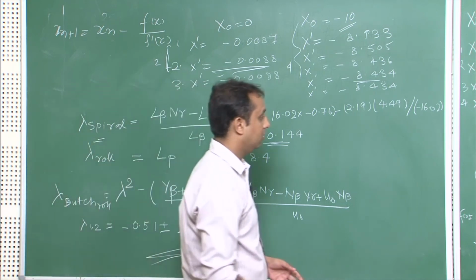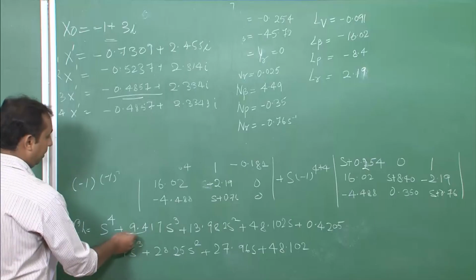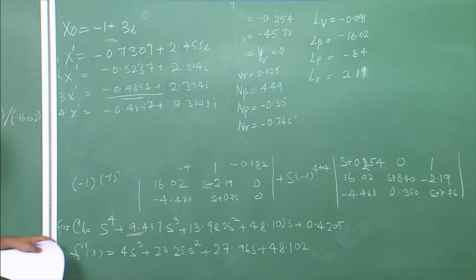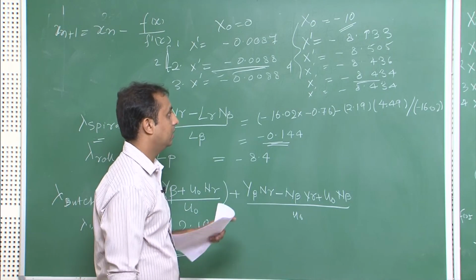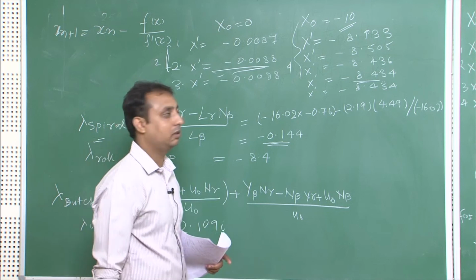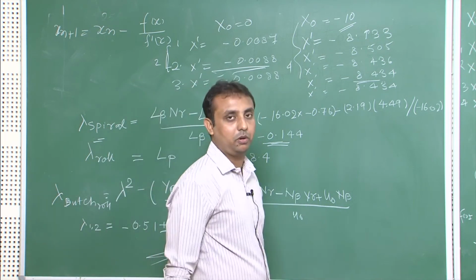There are other ways you can approximate this. Since this is for lateral dynamics, you can use two first order equations and one second order equation, then equate the coefficients, but it is very lengthy, and the solution will also become a fourth order equation, so you won't reach anywhere. So this is a better method to calculate the roots of any nth order polynomial.